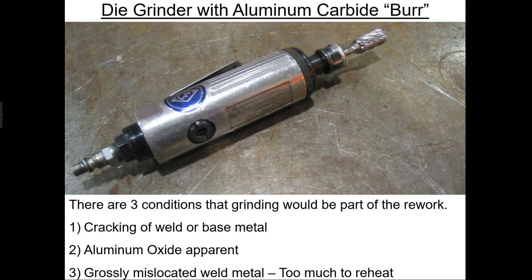If you have a crack that extends outside of that zone, we have specific instructions from the OEMs to make sure we do not put weld in a place where weld is not supposed to be. It's that simple. Now that actually goes for everything, but to do with automotive, that's a good rule of thumb. So if you have a crack, it has to get cleaned out.